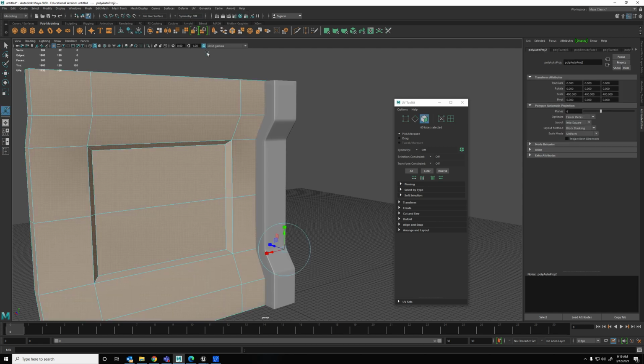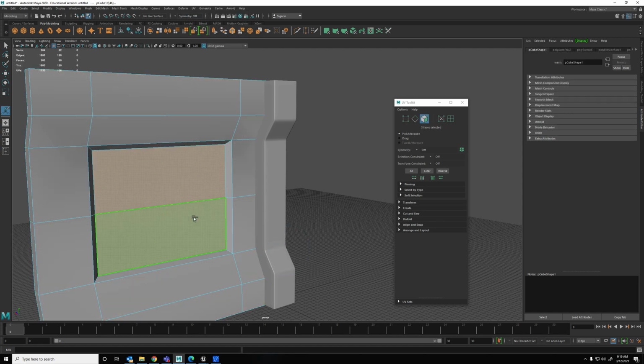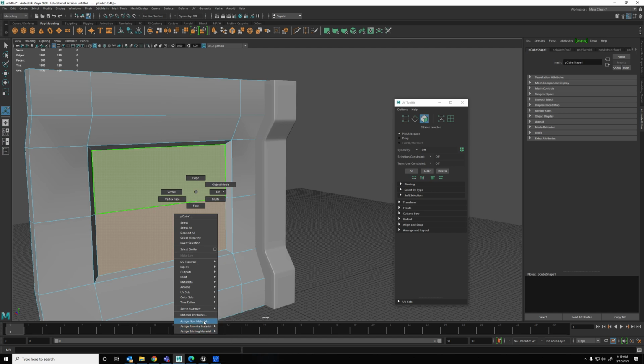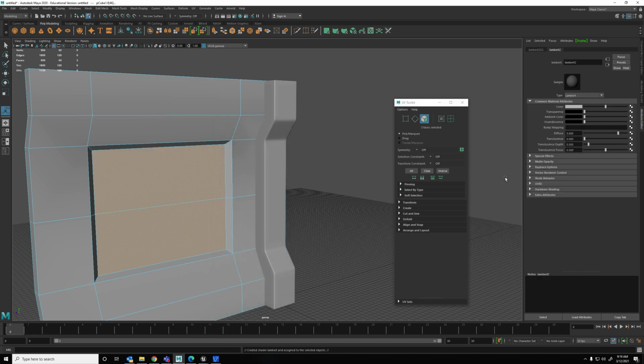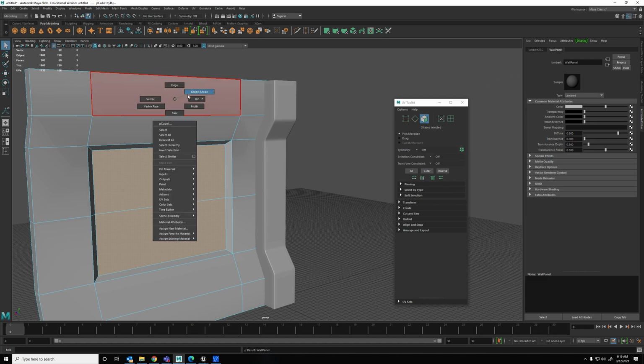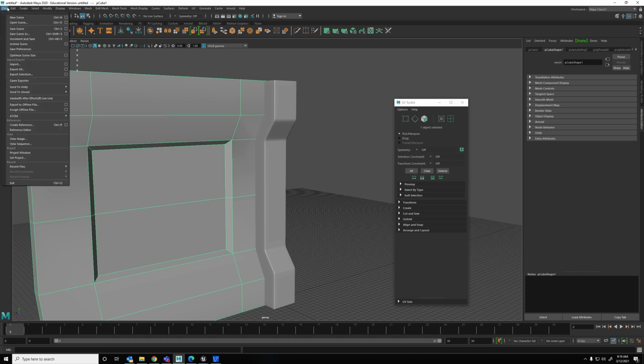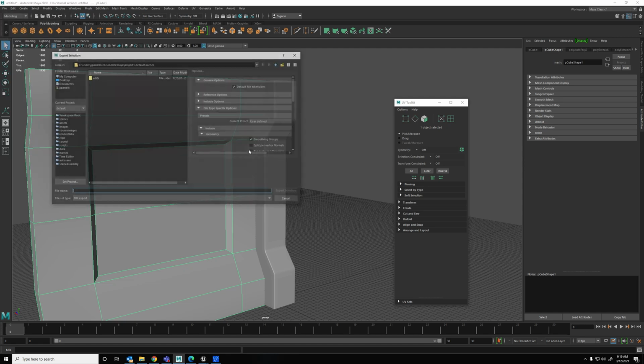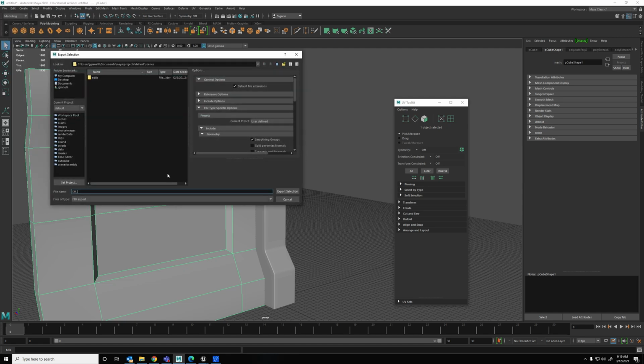The automatic. If you wanted to get fancy and make this a different material in Unreal, you could assign just these faces a new material. And I'll just put like this wall panel. And I think that'll all transfer over. So let's take this and bring it back into Unreal. Export selection. And I'll call this static mesh underscore wall panel 400 by 400. I'll just stick it on my desktop because I'm unorganized. An FBX is what you want here. And make sure you check smoothing groups.